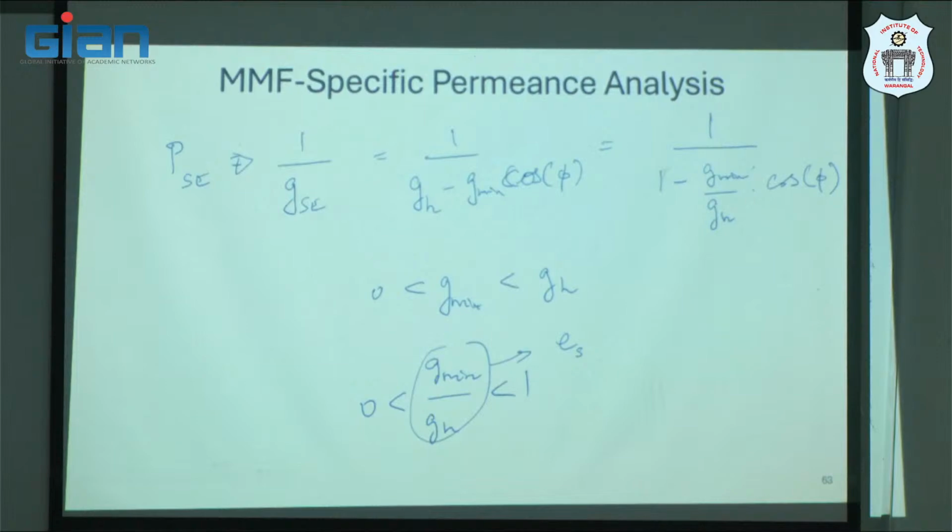In the example values I have chosen, when we have 5 mm minimum gap for a 10 mm uniform gap machine, the severity is 50%. 50% is very high. When the severity percentage is less than 10, it's very small.